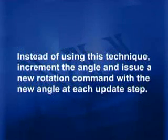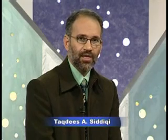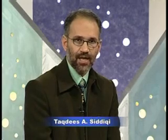So instead, we can increment the angle and issue a new rotation command with the new angle at each update step. So the idea is that rather than successively providing those rotation commands repeatedly, we issue the rotation command from scratch using an incremented angle value, and that is going to ensure that our reference would be sane and we are going to get healthy results.